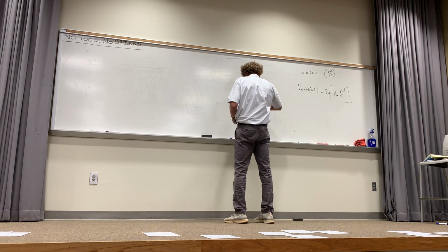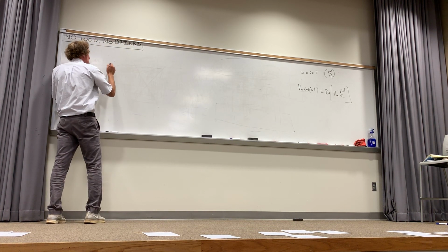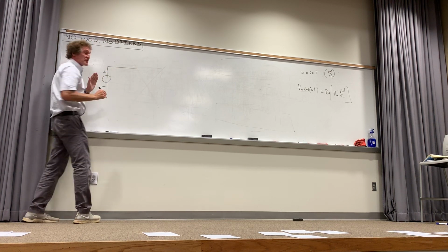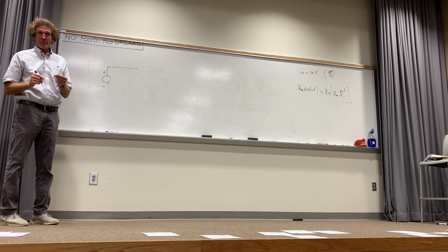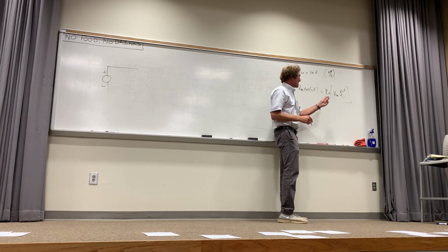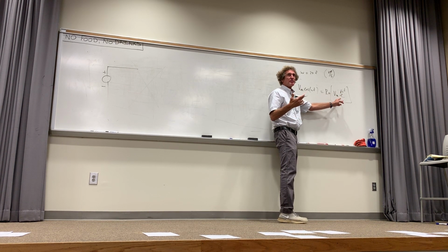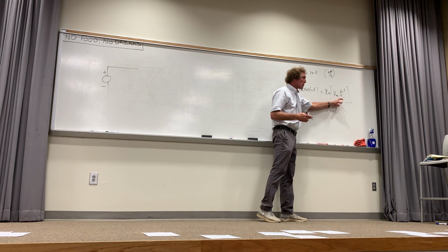So, here's some things to know. I'm going to have this circuit. Remember, anytime I want the actual response, if I say I have a source voltage Vm e to the j omega t, the observable part of that is the real part of that. That's the actual time variation of the source I want. Do you follow me?